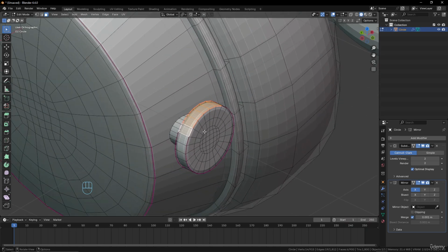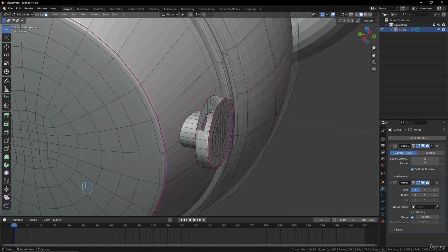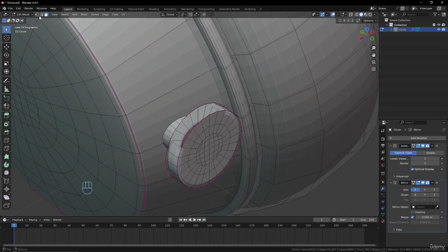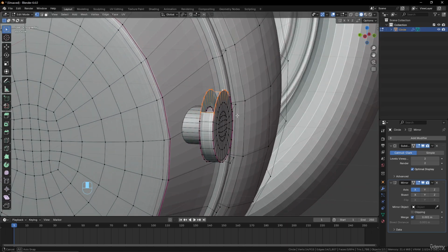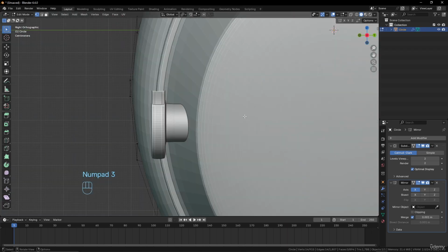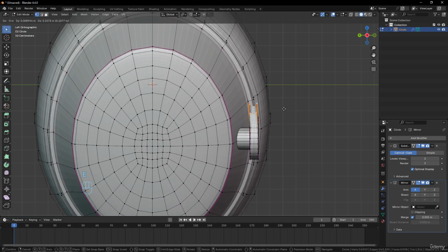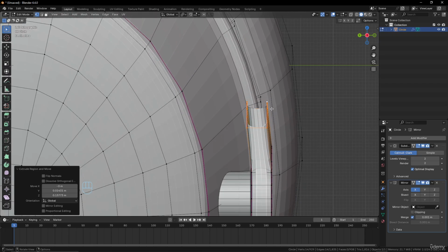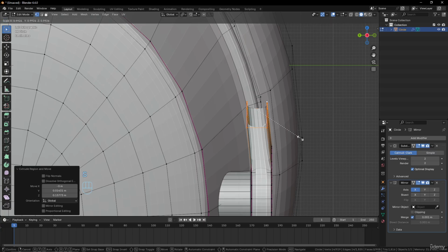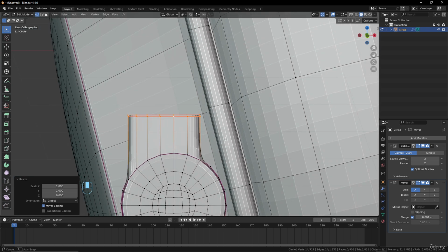And so I will remove the faces here. By removing these faces, I will have a new loop that I can select. You can see that now I can select that loop here, okay? And if I extrude that in side view, so Ctrl+3 to have the right view here, I can extrude that this way and make a little rotation. So what I do usually before making the rotation, to have a good loop, I make S Z 0 here. Like this, I come back to this kind of shape and it will look better, okay?